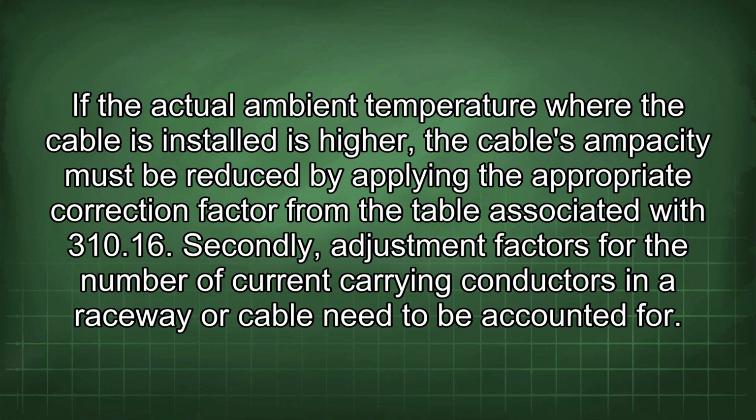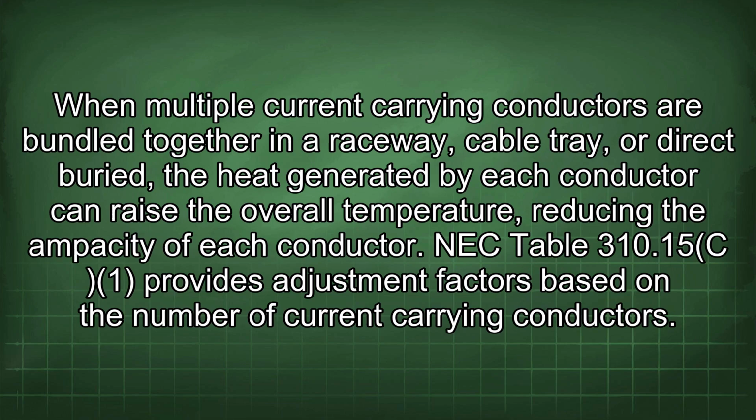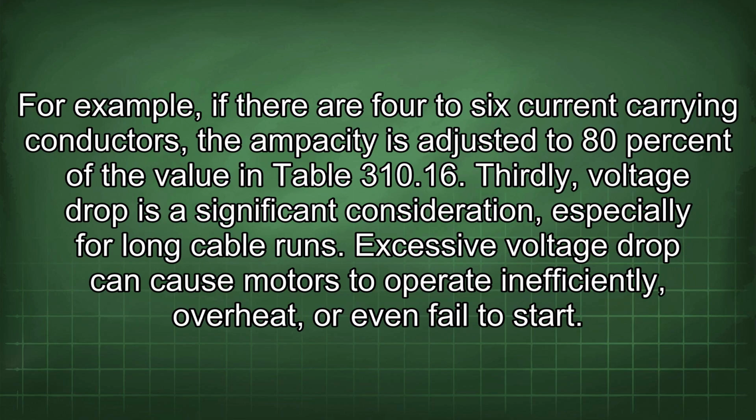Secondly, adjustment factors for the number of current carrying conductors in a raceway or cable need to be accounted for. When multiple current carrying conductors are bundled together in a raceway, cable tray, or direct buried, the heat generated by each conductor can raise the overall temperature, reducing the ampacity of each conductor. NEC Table 310.15 provides adjustment factors based on the number of current carrying conductors. For example, if there are 4 to 6 current carrying conductors, the ampacity is adjusted to 80% of the value